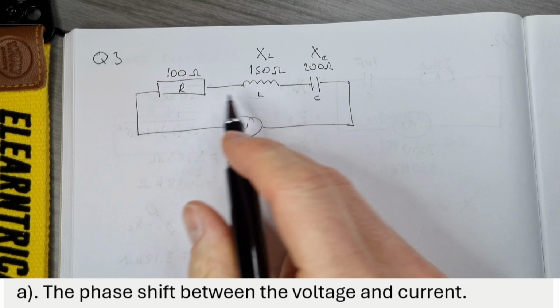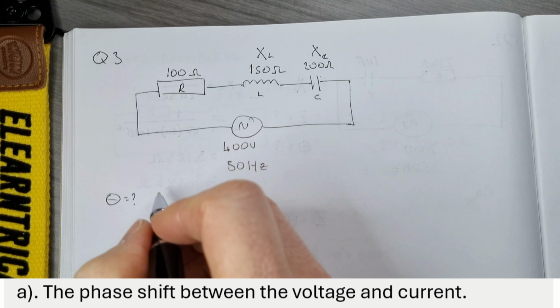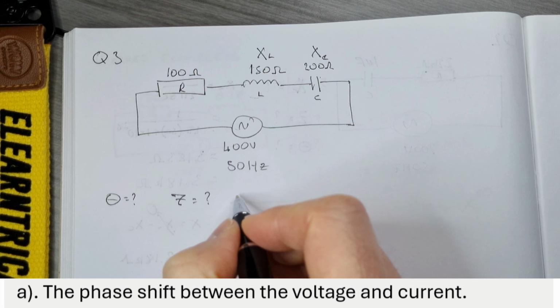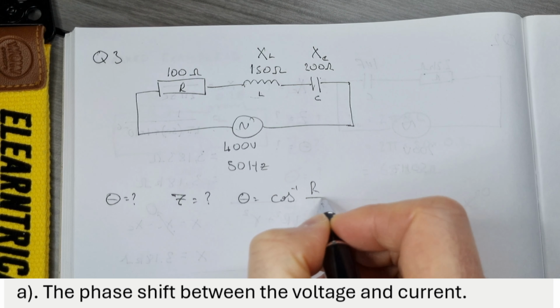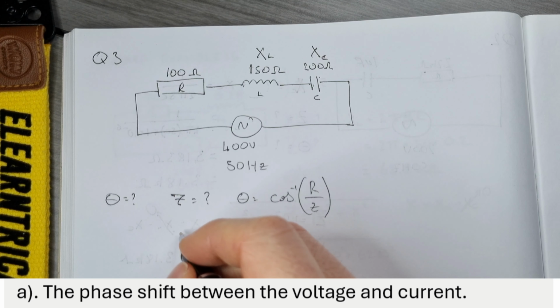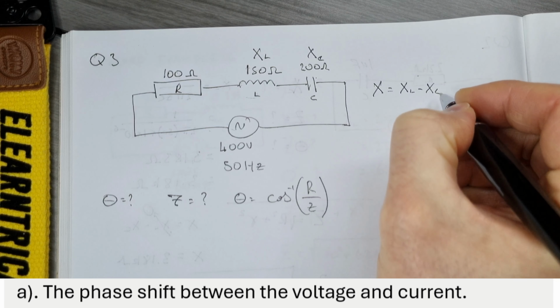To work out the phase shift, theta, we're going to need to work out our total impedance, Z. And with the total impedance, we can then work out our theta with cos inverse R over Z. So in this case, our overall reactance, X, will be XL minus XC.